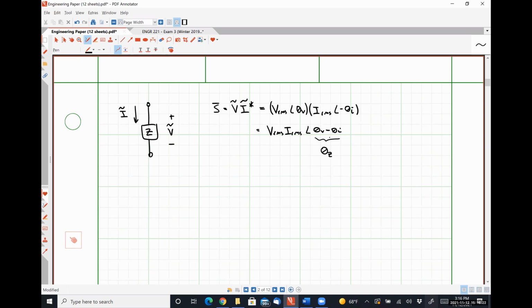Because cosine ranges from +1 all the way down to -1, it's perfectly okay to have a negative power factor. That just means it's supplying power. But when we do it from the source perspective and say, find the power factor at which it's supplying power, we're always going to wind up getting a positive number. So I won't give you anything, at least intentionally, where you'll have a negative power factor in Circuits 1.